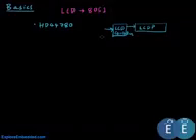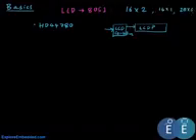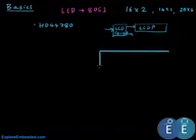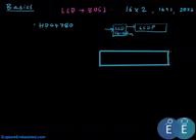In the whole tutorial, we will be discussing interfacing a 16x2 LCD, which displays 16 characters on 2 lines. You can as well extend these concepts to 16x1 or 20x4, so 20 characters or 4 line displays. The LCD will have the following pins.